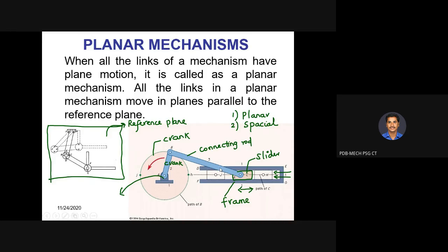Okay, if you assume it is a compressor instead of an IC engine, a motor will be connected here at the crank. I will connect a motor here, and the crank will rotate continuously. When the crank rotates, your connecting rod is connected to the slider, so that your slider is going to make to and fro motion. So here air comes in at the inlet, and compressed air goes out at the outlet. Okay, so this is the basic operation of this particular mechanism.